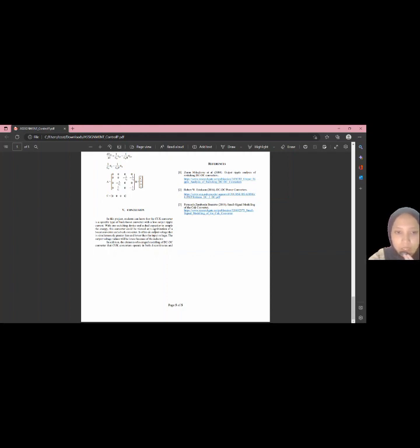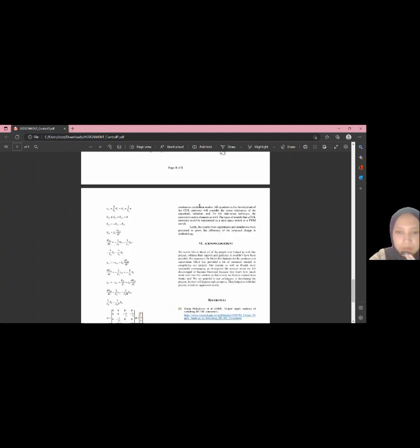In addition, for the average modeling of DC-DC converters, the Cuk converter operates in continuous conduction mode. All equations in the development of the converter will consider the series capacitor and inductor for the state space technique, and the converter active element as well.